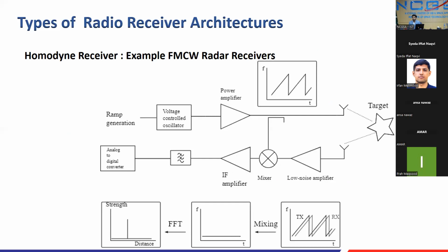received frequency will be near DC. So what happens in an FMCW radar system is you have DC to some few megahertz of beat frequency. The higher the beat frequency you receive at the IF, the farther the target will be. As the target comes closer in, your frequency gets closer to your DC point.